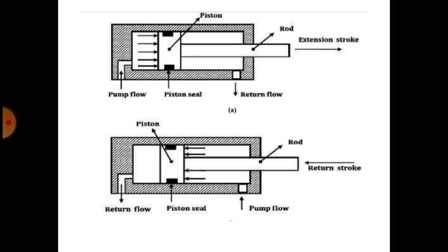It has a cylinder barrel, piston and piston rod. Both the ends are sealed with end caps, which are either threaded or welded to the main cylinder. In some designs, the end caps are held with the cylinder by tie rods. The piston is provided with a piston seal, while the rod is provided with a seal, bearing and rod wiper, whose functions are the same as those explained under the single acting cylinder. Oil ports are provided on either side of the piston so that the fluid pressure can be applied alternatively on both sides.